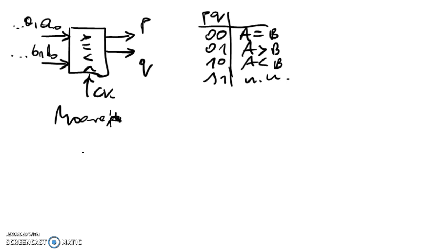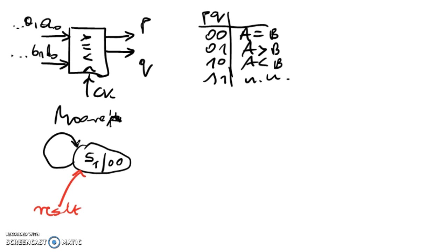We start with the initial state, which is let's say the equality state. Let's name it S1. When there is 0, 0, you start with this signal after reset. Then, if you've got the same bits of A and B, so 0, 0 or 1, 1, you stay in this state, okay? Because they're still the same after putting the consecutive bit.